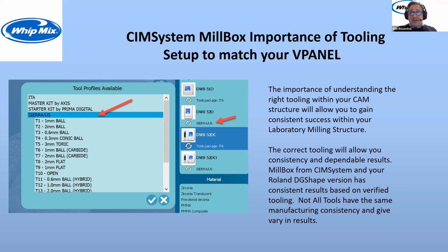And what it will do is it will cut down rapidly to the project through the PMMA because of its size and its aggressive nature. And it will save your smaller tools from doing all that cutting. So you're going to have this one big tool doing all the roughing and all the rough detail work, get down to the project, and then use the smaller tools to finish off the rest of the project and the strategy. Hence, you're saving time because you've got a bigger tool doing all the roughing, and you're saving on tooling as well. You're not breaking small 2mm tools. You're not breaking 1mm tools. You're just adding to your productivity with this larger tool.